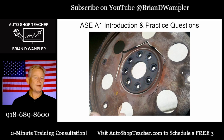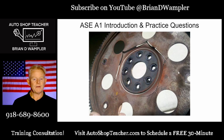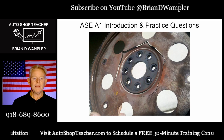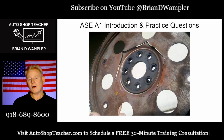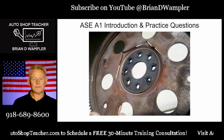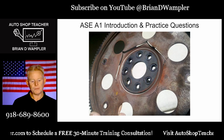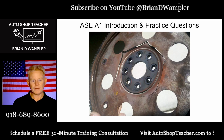It's different than a flywheel. It's in the same location between the engine and the transmission, but we have a flywheel when we have a manual transmission. The flywheel is much thicker, usually made out of cast steel or cast iron. It also has the clutch cover and disc attached to it, so there's a lot of mass there with a flywheel. We don't need that much mass when we have an automatic transmission because the torque converter part of the transmission that attaches to the flex plate is quite large and quite heavy, and so it provides that mass.